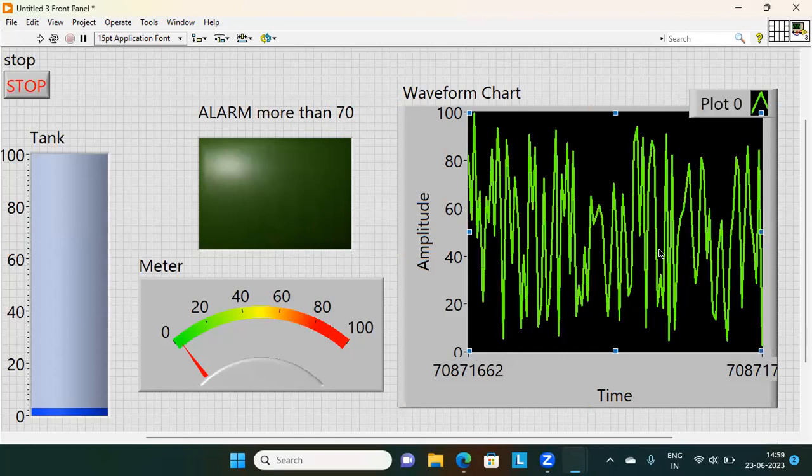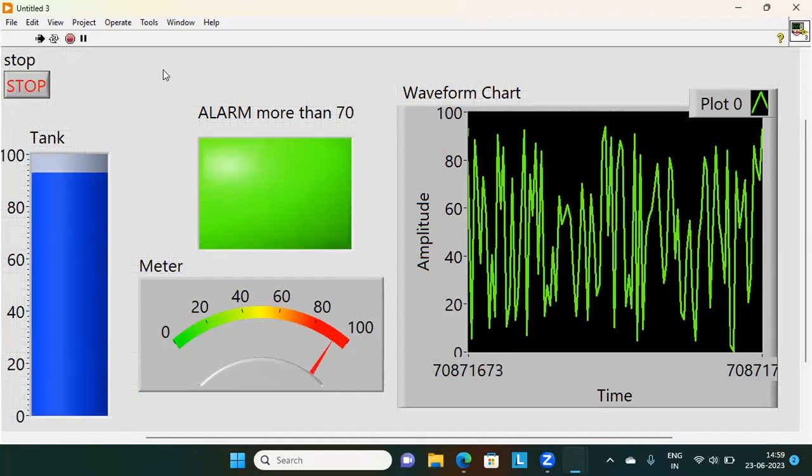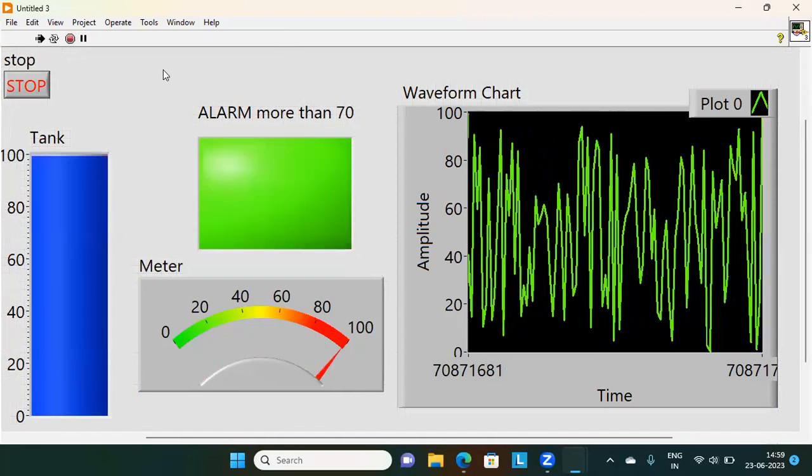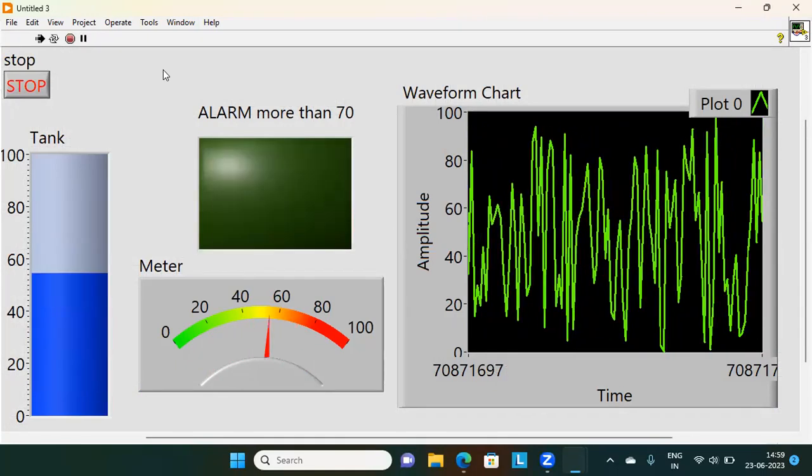So this is just some representation of data. It's nothing related to programming, it's just representation of data. And I run this program now. So now my program will be delayed by 250 milliseconds between two iterations. And clearly I can see these values. Now see, I'm running this program, so we can observe it closely. See that whenever the output goes more than 70, the LED turns on.